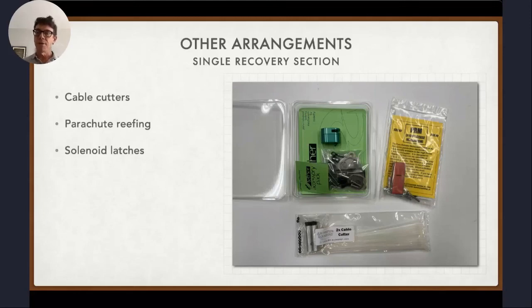No, I don't know. There's a question about an ejection charge kit. The 1.4 gram charge is a pretty big charge. That would be a fairly large rocket, so that would open up almost any rocket, maybe even too energetically for mid-power rockets. I don't know what's in it if it doesn't have hazmat, but if they've made it work, then that's great. But I have not used it. Again, I've been doing this for a long time, so maybe I'm still doing it the old-fashioned way. But yeah, the techniques that I've shown are what I have used.